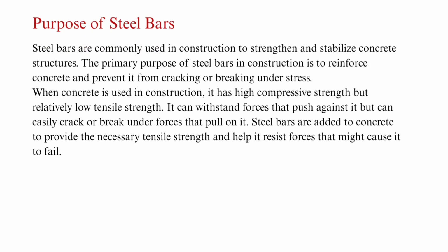Now the next is the purpose of steel bars. Steel bars are commonly used in construction to strengthen and stabilize concrete structures. The primary purpose of steel bars in construction is to reinforce concrete and prevent it from cracking or breaking under stress. Concrete has high compressive strength but relatively low tensile strength.